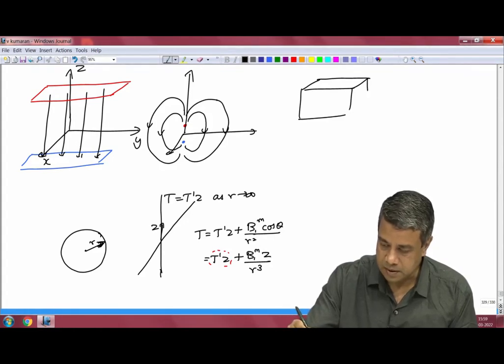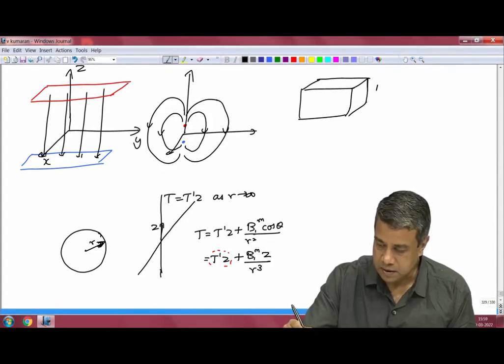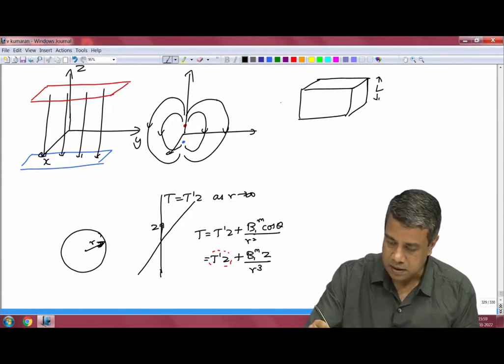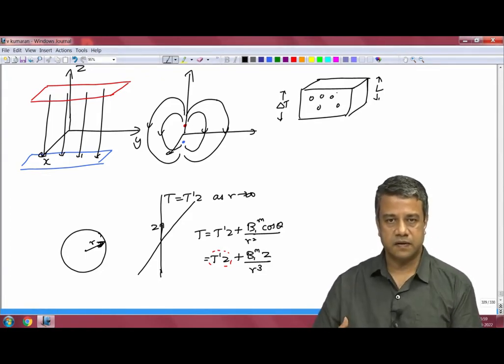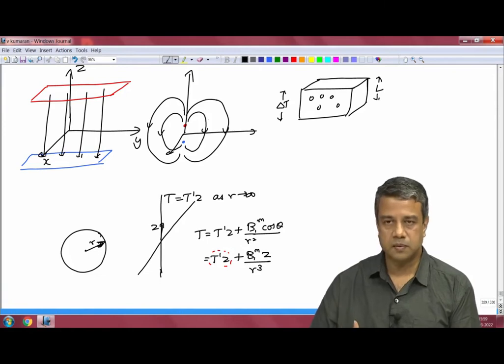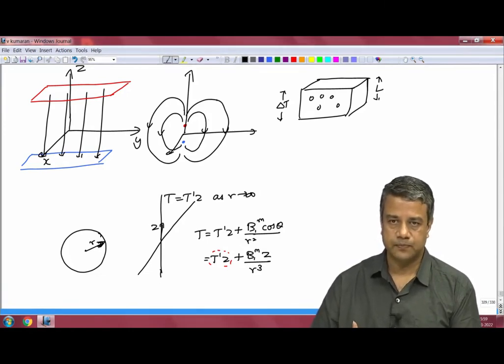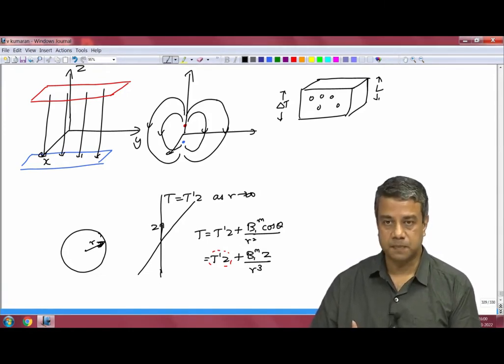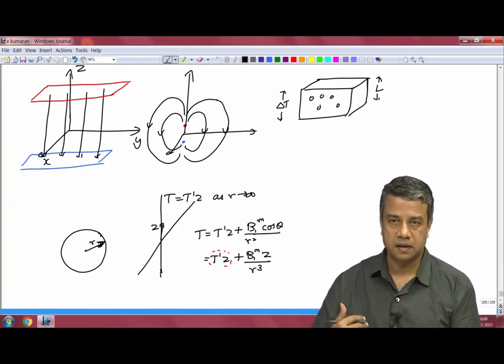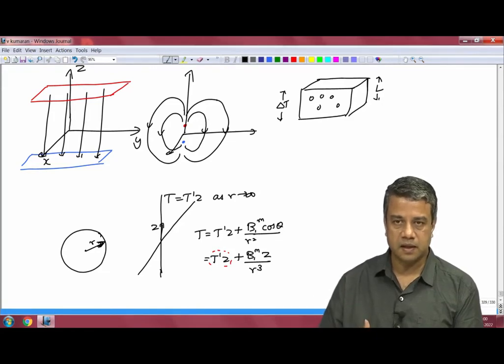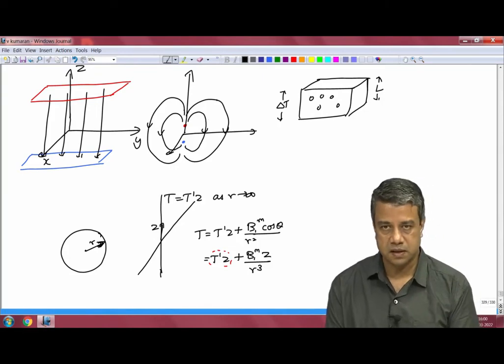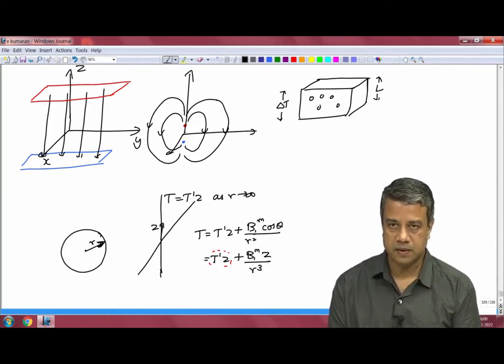This was obtained by applying a temperature difference, delta T, across the composite of a distance z, and in that case you get linear flux lines far from the particles. Close to the particles there is going to be a disturbance, since the applied temperature field has the symmetry of the growing harmonic corresponding to the dipole: two plates separated by a large distance, with a constant flux in between.